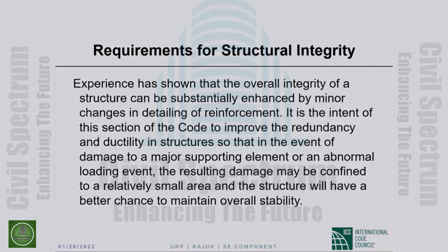The reinforcement, tension reinforcement is the most effective when it is close to the tension face. So it will be in your interest to keep the layers as close as possible, not violating that 1 inch gap. So there is no upper limit because who would think of putting an upper limit? It is in your interest to keep the layers as close as possible to the tension face.